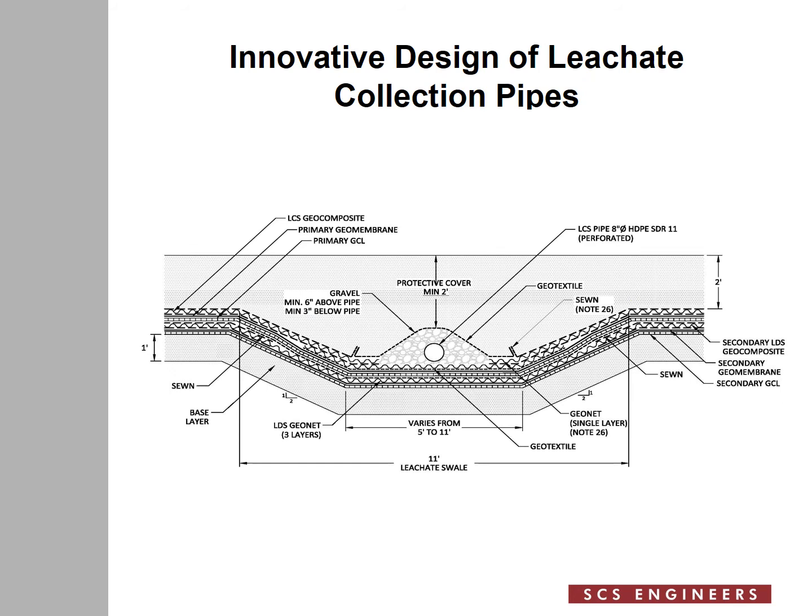The innovative design for the leachate collection pipe is presented in its detail. Again, I would ask you to ignore the type of lining system. It's basically still a trench in the middle, and the geocomposite coming from both sides into the trench brings leachate toward the leachate trench. In this case, we still have pipe encased in gravel, and the gravel is covered with textile.